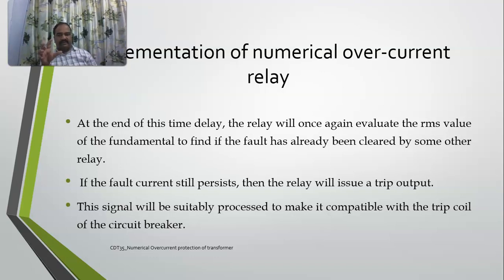So you need to wait for 3 seconds once your condition is checked. At the end of this time delay, the relay will once again evaluate the RMS value. Still after 3 seconds, if it is greater than your pickup value, now the relay will issue a trip output.